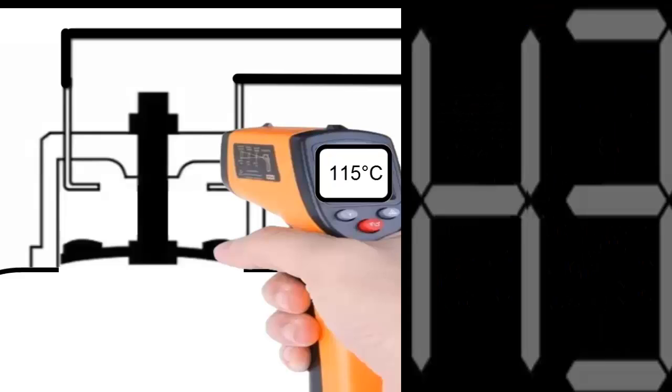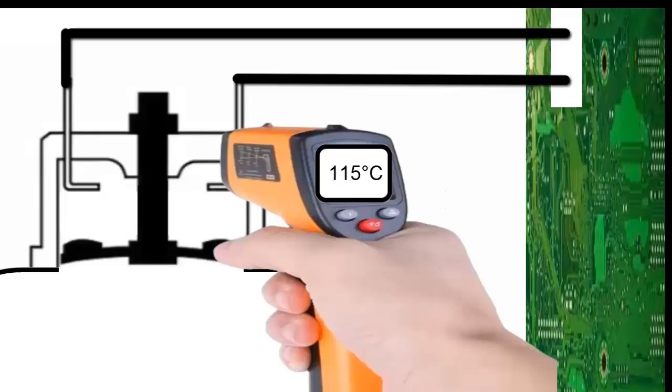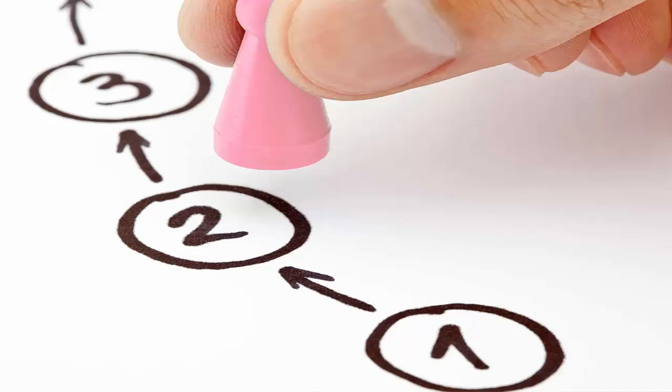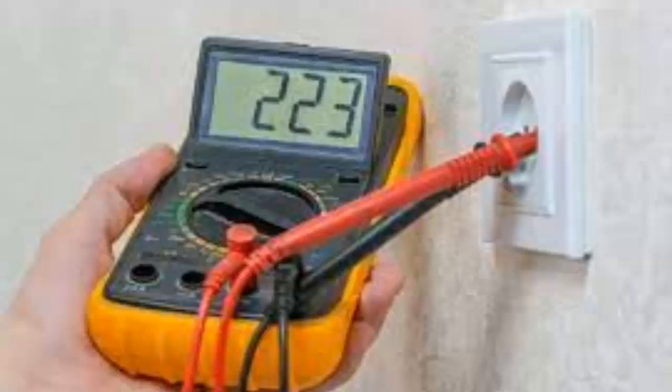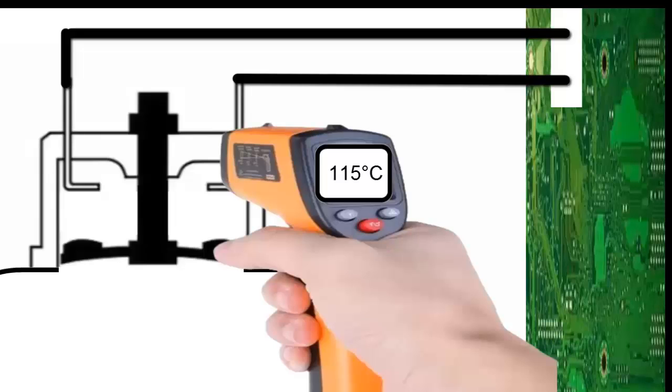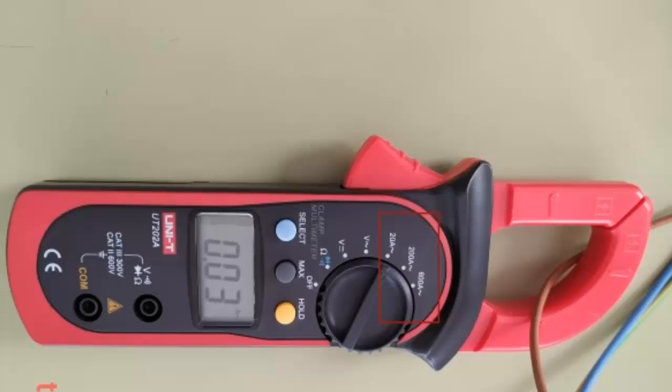How to fix the H3 error in air conditioning. The solution to the problem depends on the cause of the error. It is recommended to follow the following checking order. 1. Check the power supply voltage from the external electrical network. 2. If you have an ammeter clamp, measure the equipment's current consumption from the electrical network to check for excess current presence.